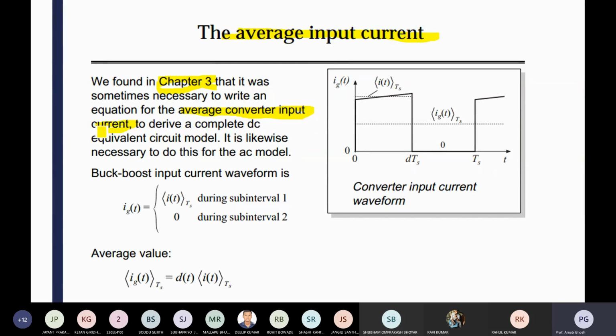In the presence of this charging and discharging current, you also observe the ripple of the converter. There is an effect on the ripple of the converter, and that ripple is significant. You can see the ripple is significantly high, which totally depends upon the slope of the inductor current.